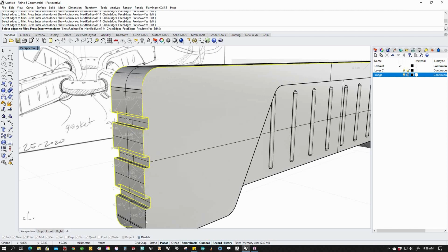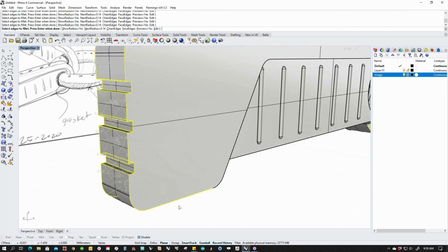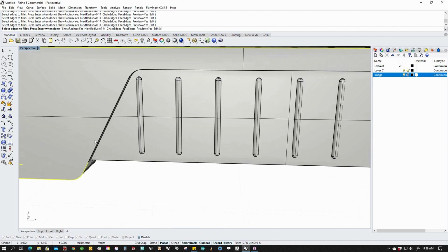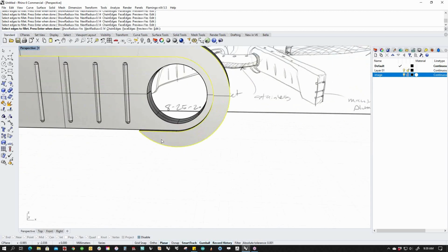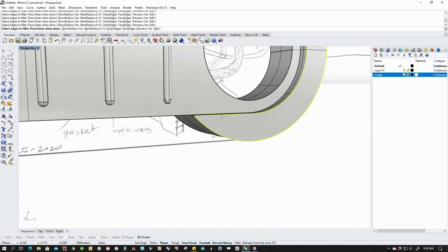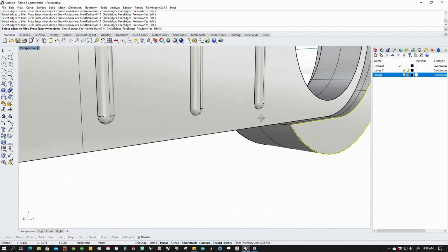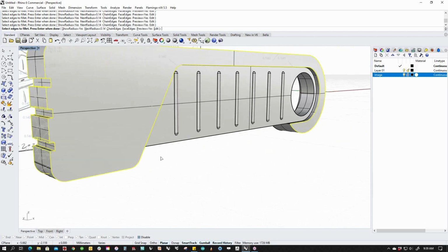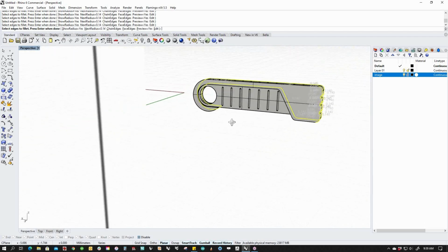And I'm going to have to use a tiny fillet because I've got some small spaces in here. I can't just go crazy and throw a giant fillet on this thing. And so I'm going to let it run out on the edge. I'm not even going to bother trying to knock this edge off because I kind of want that sharp to look like it was almost machined.